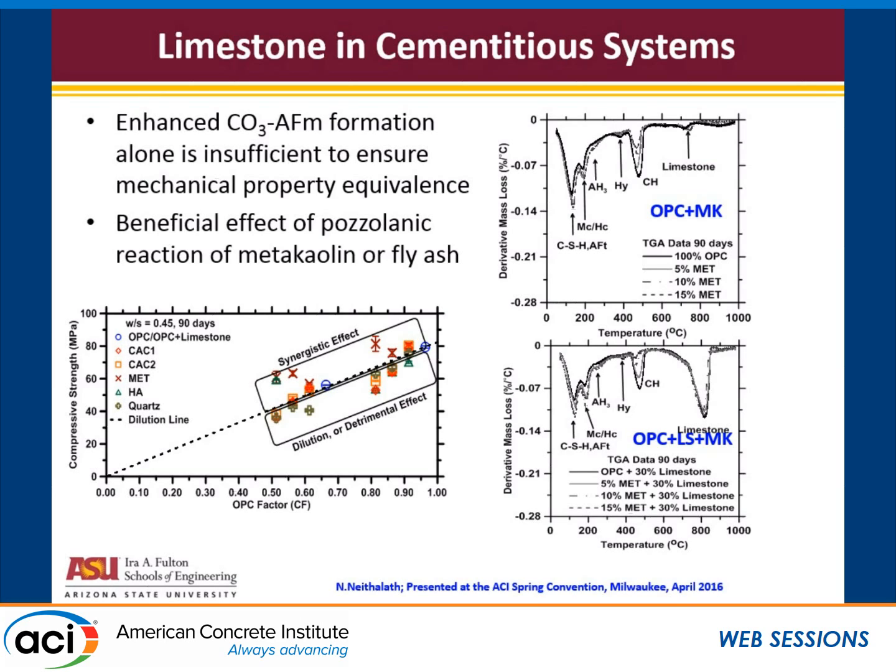If you replace, for example, it's right here, if you have got 42% of cement that is replaced with a combination of metakaolin and limestone, your strength reduction is only of the order of 20%. So you're essentially saying that you can have a large reduction in clinker factor with strengths that are acceptable if you proportion properly. Now this shows a little bit more of chemistry of what happens here.